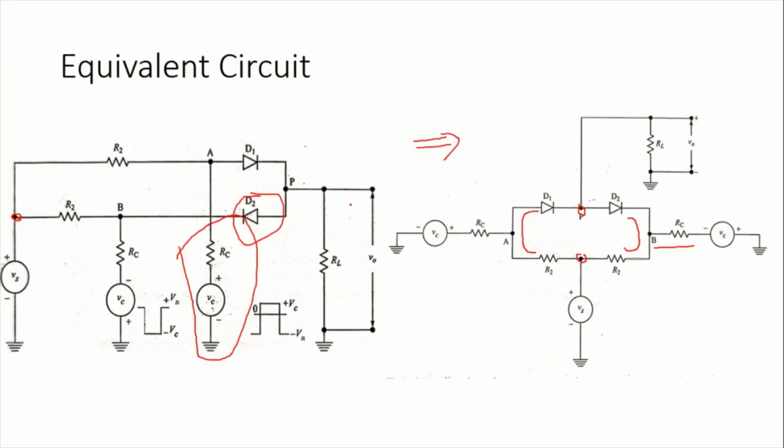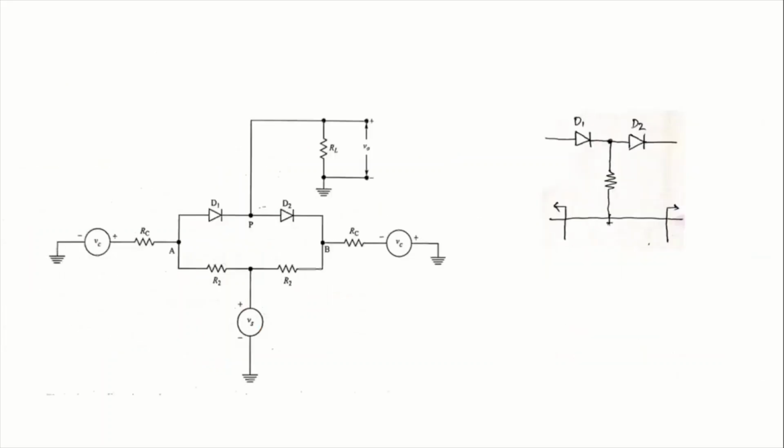To find the gain of the circuit, we have to reduce it using a Thevenin equivalent. How to reduce? Let us see. To identify the output in terms of the input, let us replace this circuit with the Thevenin equivalent as shown in the figure. We need to identify the Thevenin resistance looking out from the input signal side towards the output side.